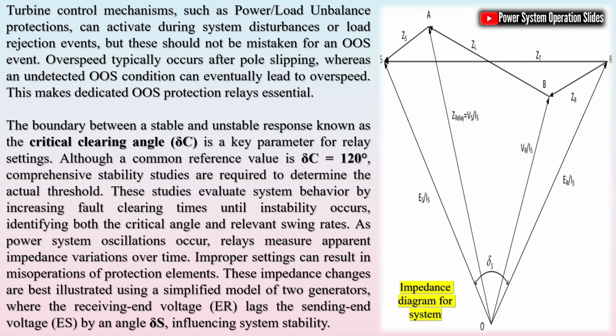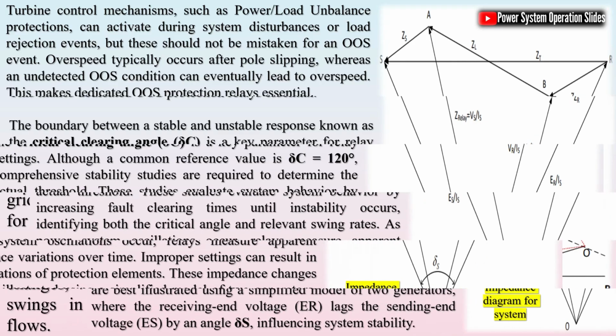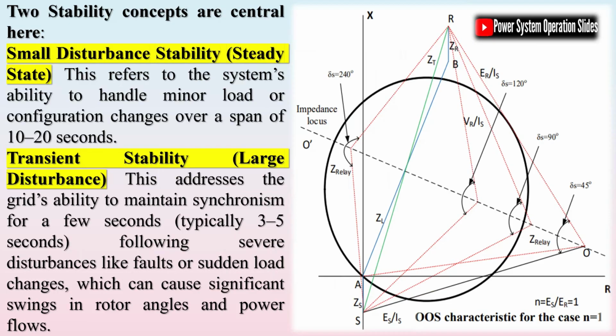Out-of-step protection serves two primary functions. The first is tripping protection, which differentiates between stable and unstable power swings and initiates network sectionalizing islanding to isolate unstable areas, thereby maintaining a balance between load and generation in each island. The second is the blocking function, which prevents relay elements from tripping during normal or stable power swings while allowing operation during genuine fault conditions.